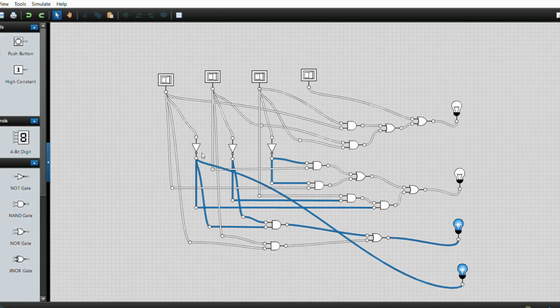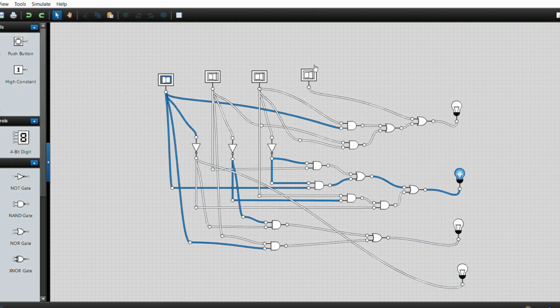So we have used 3 NOT gates and 5 OR gates, and the rest of them are AND gates, and it is used to convert the binary coded decimal to XS3. And now we will see another input for 1001. So for 1001, the output is 1100. So for 1001 in binary coded decimal, the XS3 output is 1100.